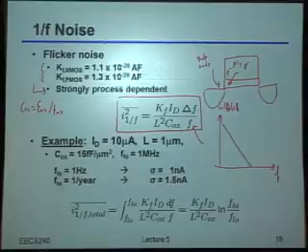Yeah, exactly. The whole trick there is that if your oxide is thinner, the gate oxide capacitance is larger, meaning that for the same voltage applied to it, moving one electron in and out, relatively speaking, has less of an effect, because you had more charge to begin with. So the other way you said it was that one charge has less of an effect on the threshold voltage. Okay, that's indeed exactly what it is. The thinner the oxide is, the less one charge could modulate the threshold, and therefore the smaller an absolute current density variation you should get. Okay?